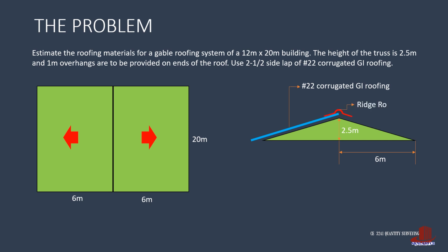On top of the truss is the ridge roll. Then, a fascia board is also placed on the ends. The common size of fascia board is 1 by 8 inches. The roof sides require gutters, and the ends would take flashings.